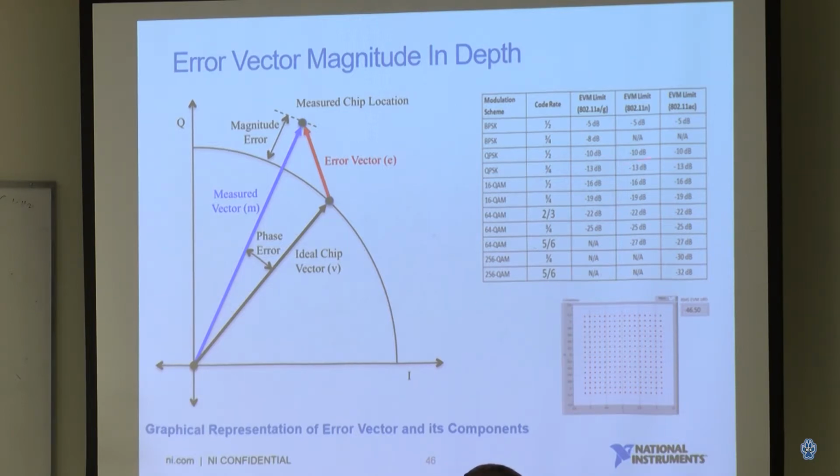And this is just the general requirement, it doesn't mean you only need to hit it, right? As a rule of thumb, you need to be 10 dB better than this number. So let's say you are a vendor trying to build an IC to generate a 64 QAM signal. You'll need to hit 35 dB, not 25. You have to be 10 dB better than the 3GPP requirement.